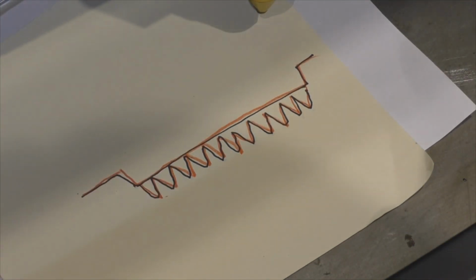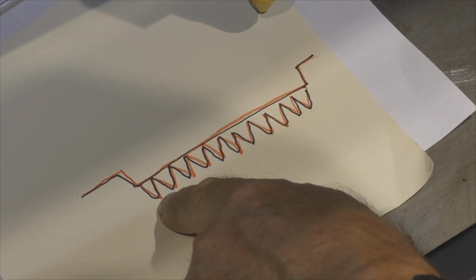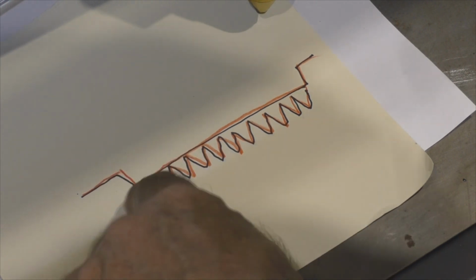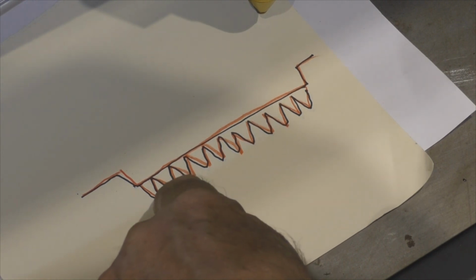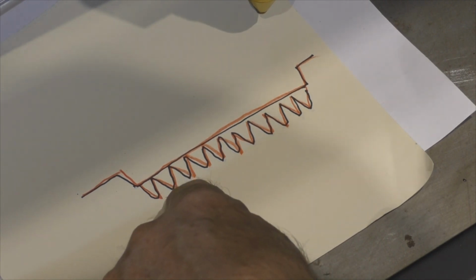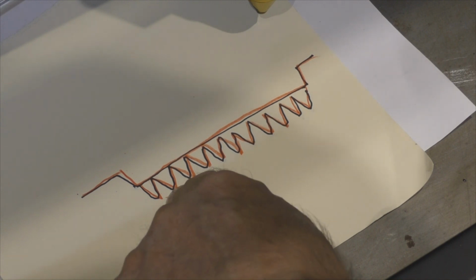We can't have additional power because the power is steady throughout the cut. So the only thing that can be causing this is the cut is stopping, and that's allowing the burn to go deeper, and then it's accelerating and moving on to the next position.